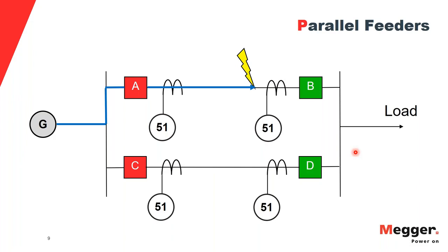So the first breaker, since the fault is near breaker B on transmission line A and B, I would have my breakers B and D tripped because the fault current is higher than the pickup. So after a time delay, I would trip B and D. And I have my breakers E, A, and C as my backup breakers.